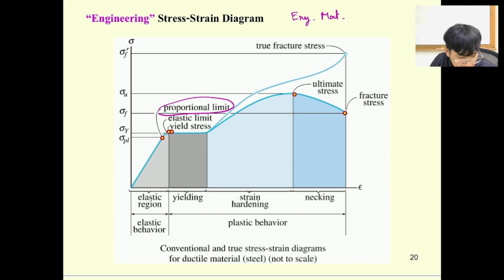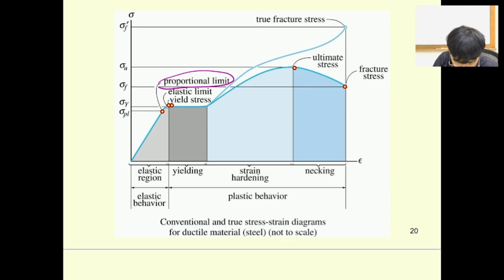This zone is basically the elastic region, which means if you apply load and release the load, it comes back to the same point. When you apply the load beyond the yielding stress over here, it's still going to deform a lot, which means you're basically rearranging the grains inside, and it's going to produce a lot of deformation at the yielding state.